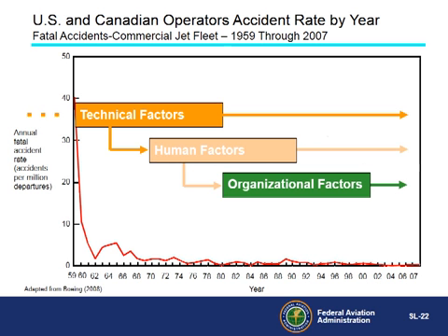The current paradigm shift focuses on organizational factors. Over time, through observation and the study of human factors, some in the aviation community began to consider whether there were underlying factors that put pilots and other aviation personnel at risk for making errors. The chief focus became how well does the organization support the employee? Factors include increased globalization of aviation suppliers and services, resource limitations, time and on-time pressures, organizational management, and organizational culture.